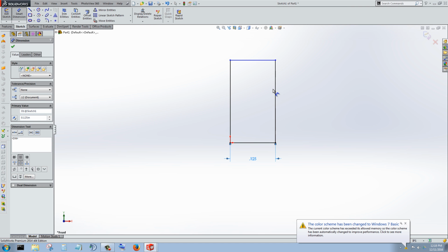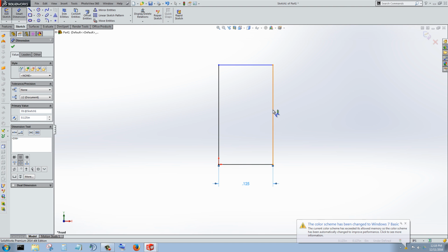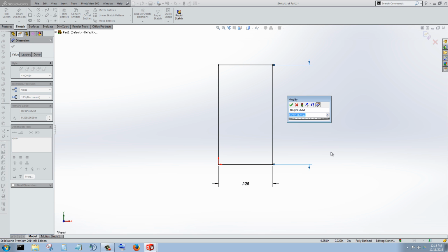Alright. So if we're 1/8 of an inch at the base, and the reason I did 1/8 of an inch is we're going to revolve something. I'm going to draw half of the pawn and then revolve it around this axis right here. So my overall height, recall that the hole, the slot, goes down into the board 1/4 inch. So 1/4 inch of this will be buried in the board. And I don't know yet, but let's see what 3/4 of an inch overall height looks like later on.